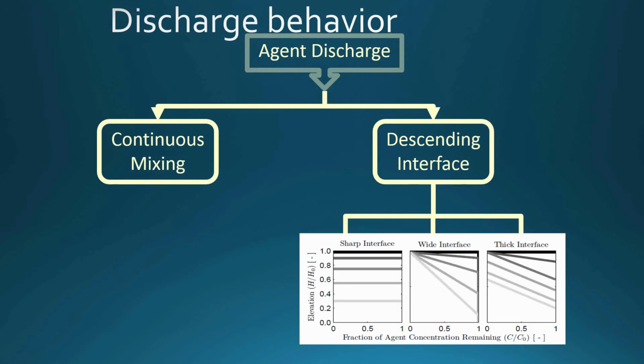The requirement for holding concentration to 90% of the enclosure height has been removed, and it's been changed to the height of the highest hazard or the equipment that's being protected.